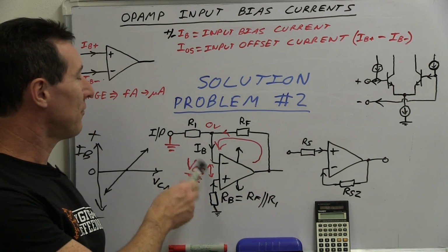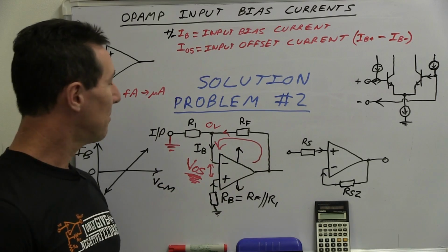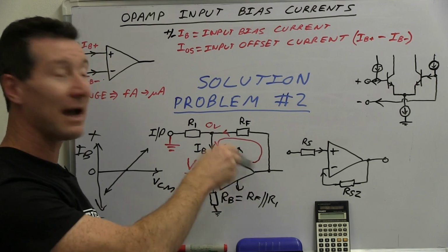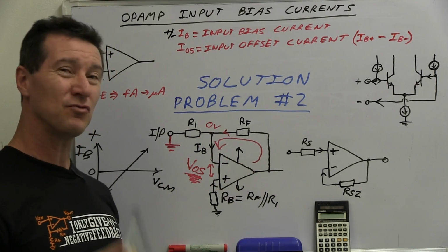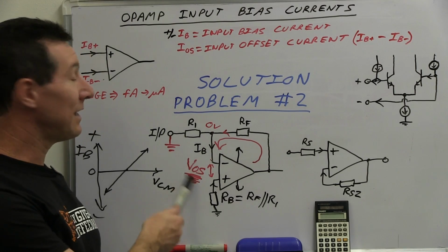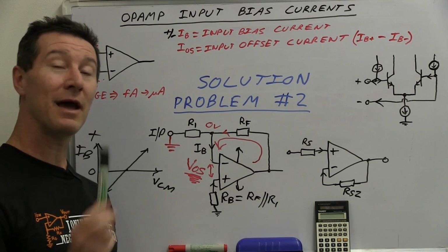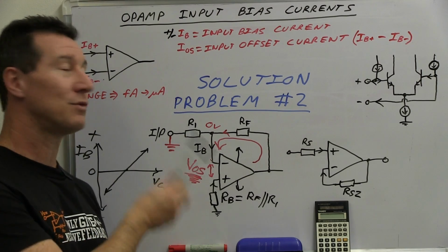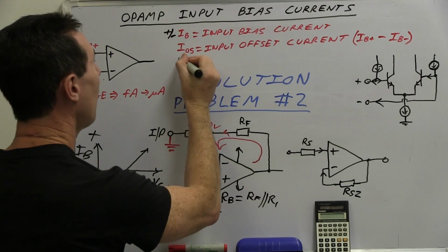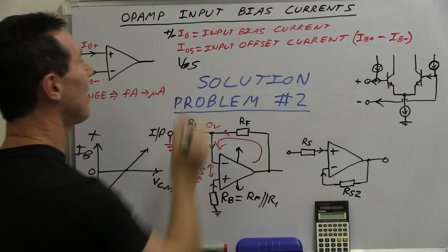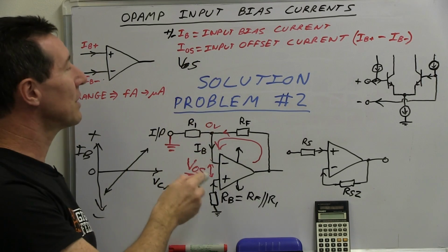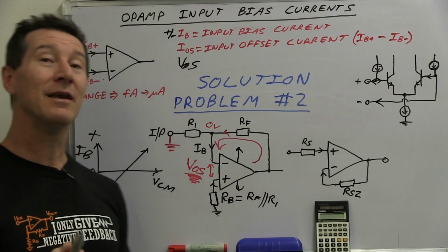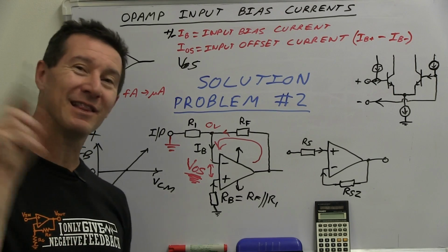And really, we're not even throwing VOS into the mix much, the input offset voltage, which is going to get multiplied by the gain of your op amp here. And it can get really, really nasty. So if you see any input offset issues, they will typically be a combination of the real input offset voltage, which is a separate parameter, VOS, an entirely separate parameter on your data sheet up here, but it can also include your input bias currents. And that's what we saw in the previous video. If you haven't seen it, link it down below.